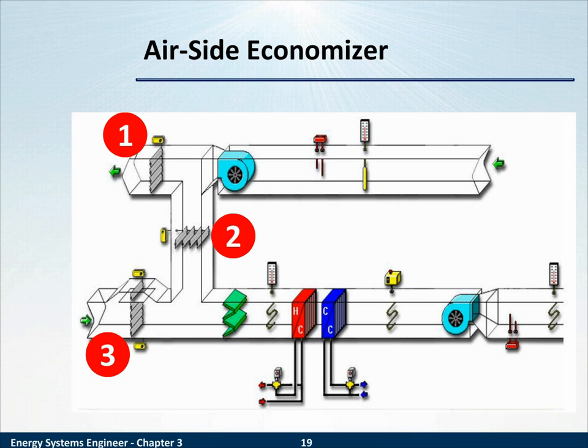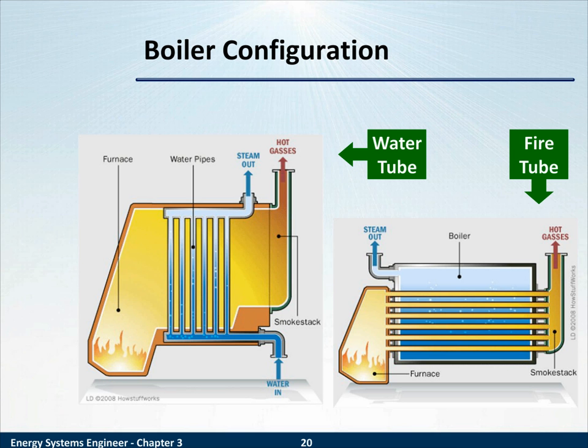That's our next topic. Let's start with where the hot water comes from. A boiler. A boiler can be used to make hot water, steam, both. And there are a couple boiler types we'll look at in a minute. But the hot water created by a boiler is pumped to the heating coil and used to impart heat to the air that passes over it.